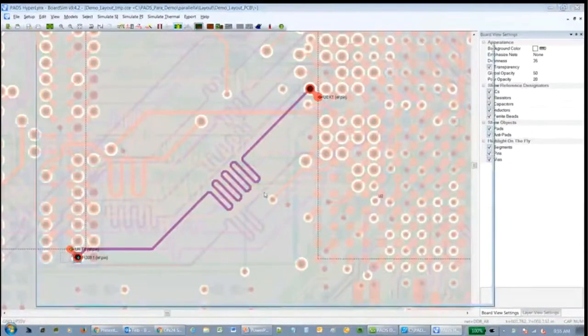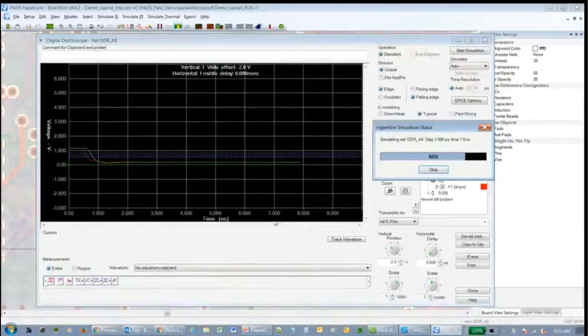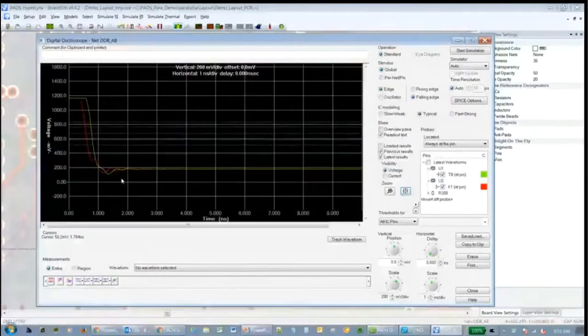So once I'm in my simulation tool here, I can go ahead and start a simulation on this. Look at the signal integrity of this net. Do I have too much ringing or overshoot? This one happens to be good in this case because the line is so short. But a lot of times the net may be too long, or I have multi-drop DDR, where I have vias. You're going to see a lot of reflections, and you'll have to play around with maybe adding some termination or changing the termination schemes on your DDR chips if you're using DDR4.